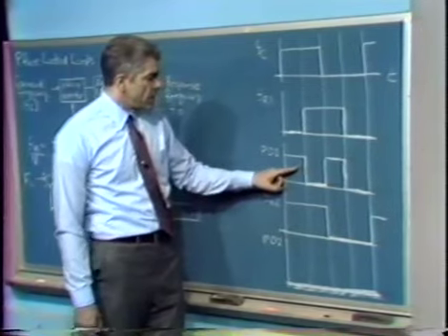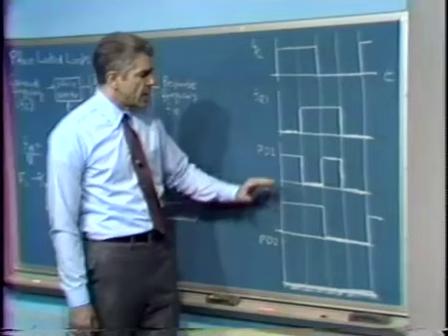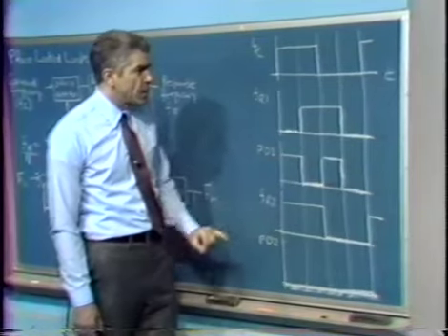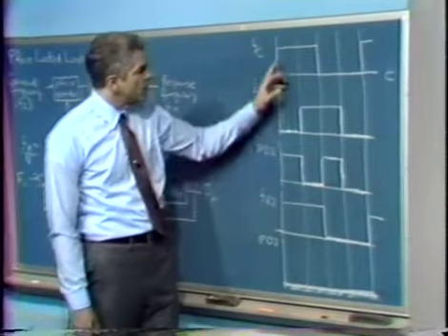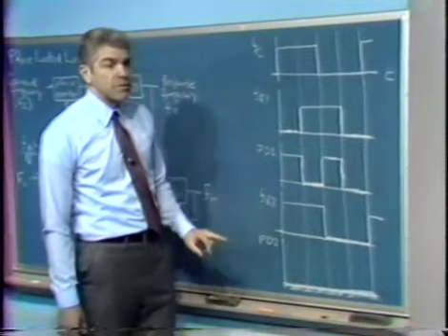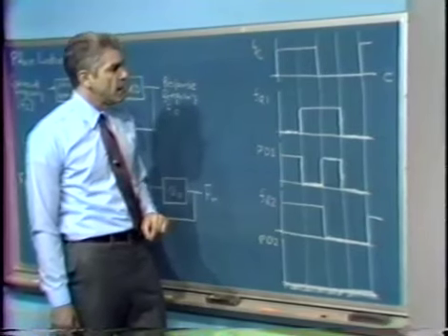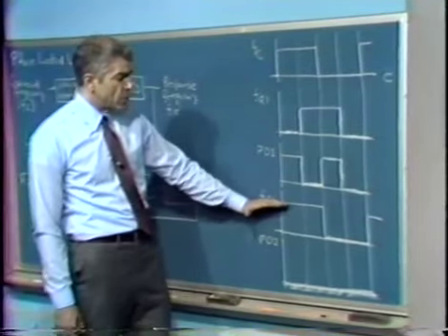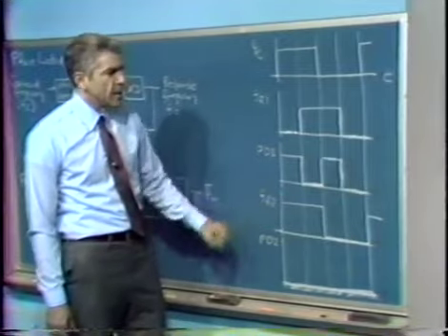If we average the output of the exclusive OR gate, when the two signals are 90 degrees out of phase, we get half of full scale. If we continued this and looked at what happened when the response of the system was 180 degrees out of phase with the command frequency, we'd find out that the output of the exclusive OR gate was always in its high state. If we averaged that, we'd get the high level.